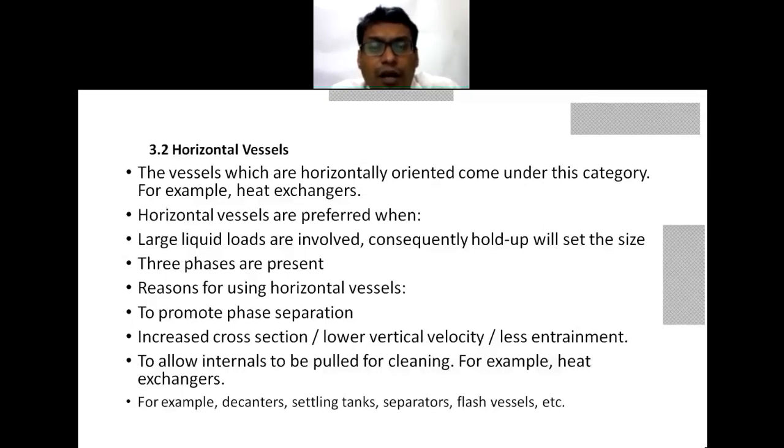The reason for using a horizontal vessel is to promote phase separation, such as solid and liquid separation. When diameters are increased, the velocity is reduced.